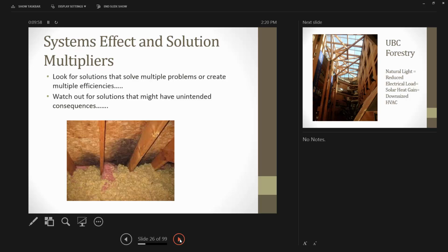So if you can reduce the BTU load of a building, you can significantly reduce the size of the heating and cooling equipment. And this has to be evaluated systematically in the most cost-effective manner. Obviously, you can spend a significant amount of money to increase the thermal envelope, but at what point is it diminishing returns?